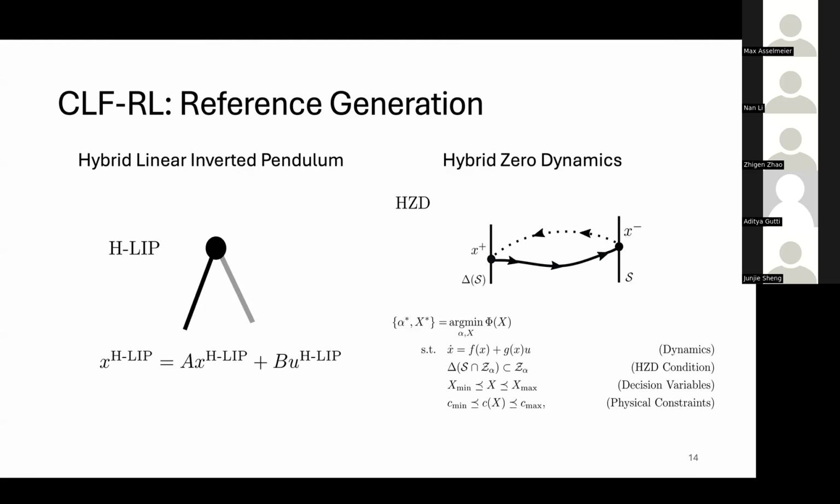So the idea is you make the underactuated coordinates stable, and then you would just have to track, and they would track these with nonlinear tools like feedback linearization or CLFs. You track the actuated coordinates. So we are doing, I'll say, the hybrid zero dynamics inspired trajectory optimization. We make a periodic orbit, and we make, in this case, a reference library. We had, I think, 10 references going from 0 to 0.75. And then we just pull the reference that's closest to the commanded velocity. And that's what we track in the training.